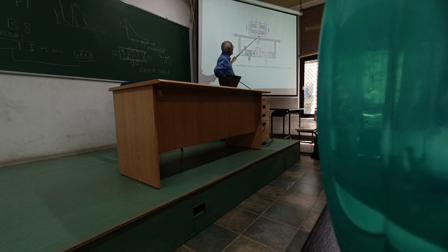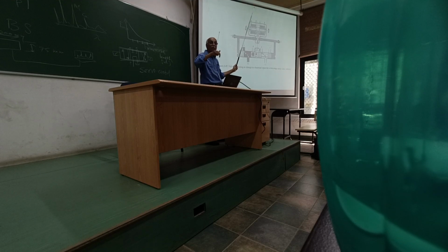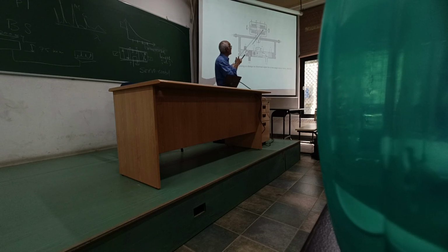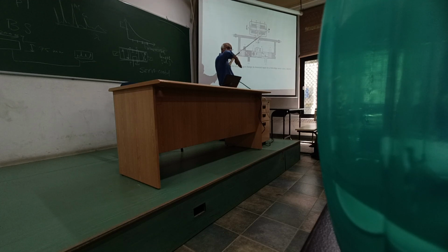Now this flapper is connected to a torque motor. So when the current over here changes, because of the corresponding north and south generation due to the direction of current, and based on the amount of current, the magnetic field which is generated will drive this flapper like this. This one, which is something like a free core, will move depending upon the magnetic field strength over here.